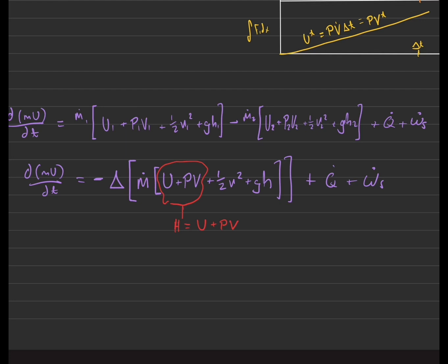Right? And again, the pressure and the volume is not a form of energy, it's a form of work. So again, enthalpy is a term of convenience and does not represent a form of pure energy. It does in part in the internal energy part, but it mostly is a term of convenience.